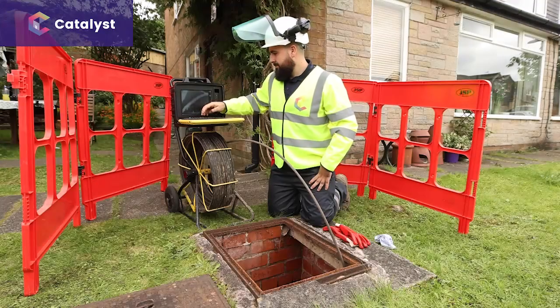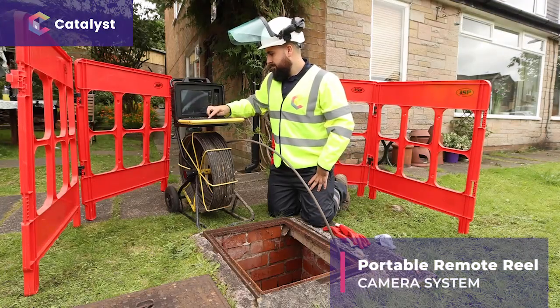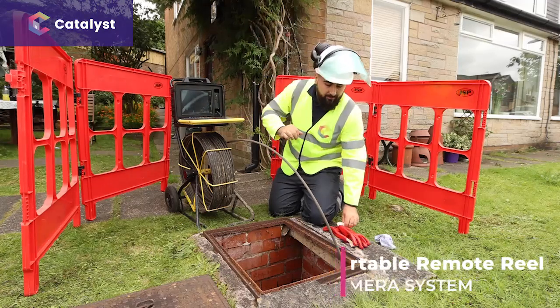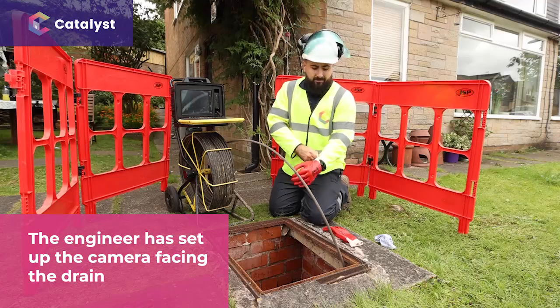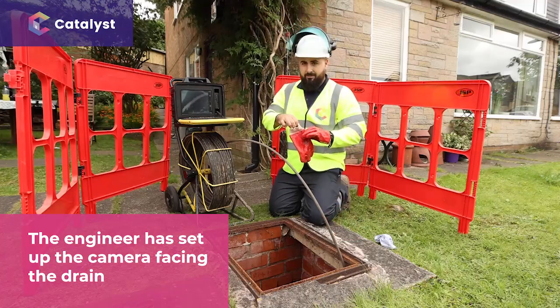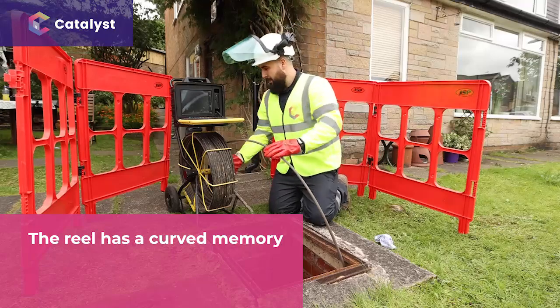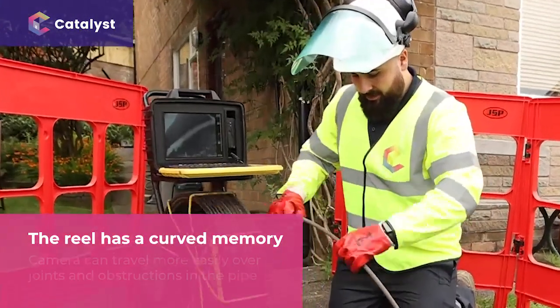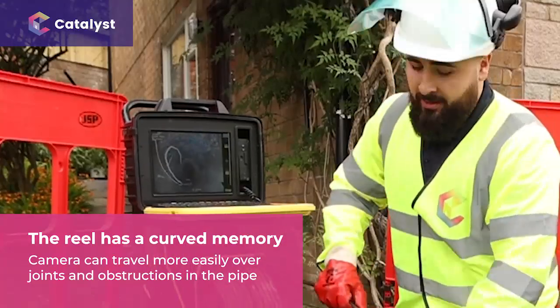For this site, we are using a portable remote reel camera system. This has a video camera on the end of a flexible cable called a reel. You'll notice that the engineer has set up the camera so it's facing the drain he's going to survey. You'll also see the reel has a curved memory from being stored on the cage. So if the camera is set up this way, it travels more easily over joints and obstructions when fed into the pipe.